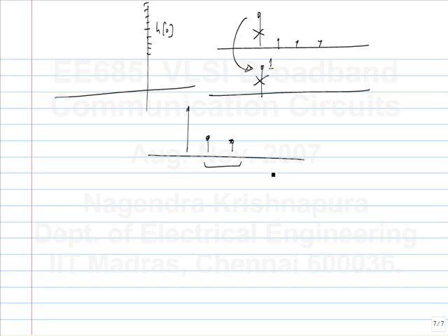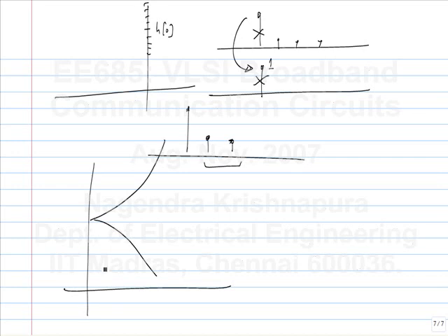But this scheme may be better for crosstalk also, for this reason. Let's say the channel has this attenuation. To boost it up, to do zero forcing, you will do something like this. To do this minimum mean square error, you may do something of this sort. Less boost. Now you also know that the crosstalk itself increases like this with higher frequencies, so you have less boost where the crosstalk is maximal. So it may do better for crosstalk as well. It will usually do better for crosstalk.